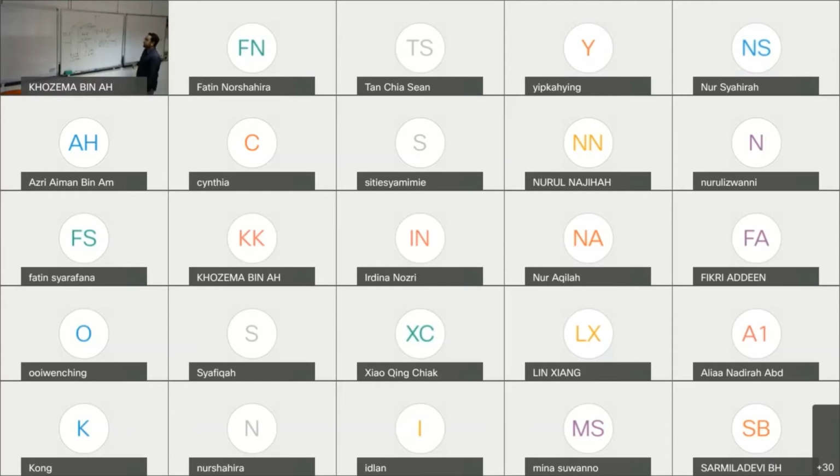And your delta T is going to be 155 minus 50. Big temperature minus small temperature. So it's going to be 105 Kelvin over the thickness, which is 0.025 meter.